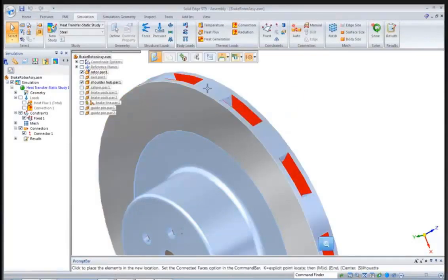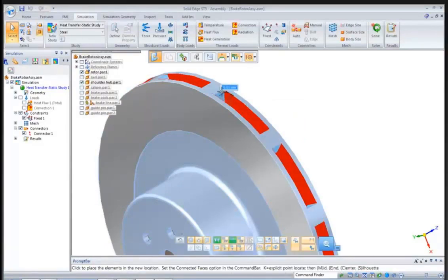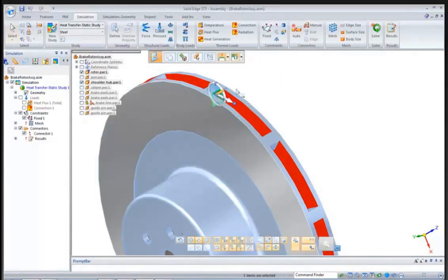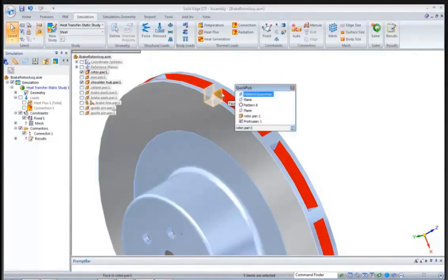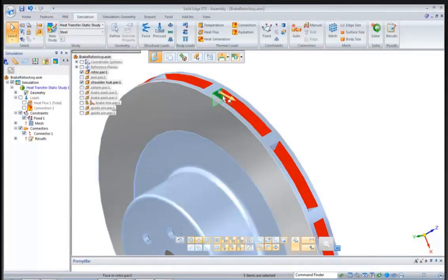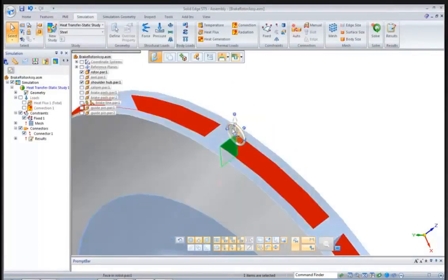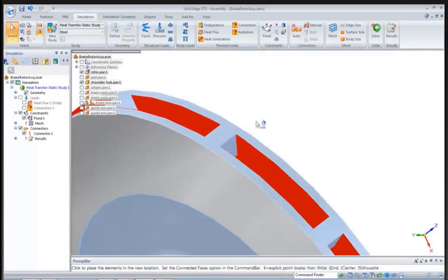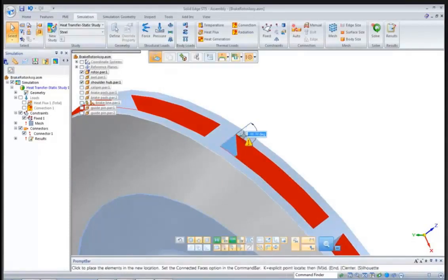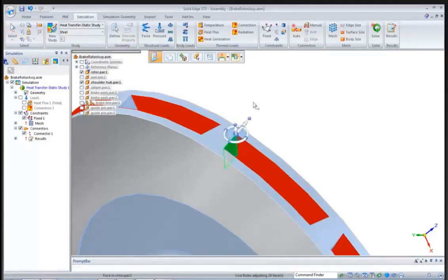I'm going to move this back using my synchronous tools, which are very handy, to, let's say, 12 millimeters. And then I also want to angle it out a little bit as well. I want to do that about 12 degrees as well. And that looks good.